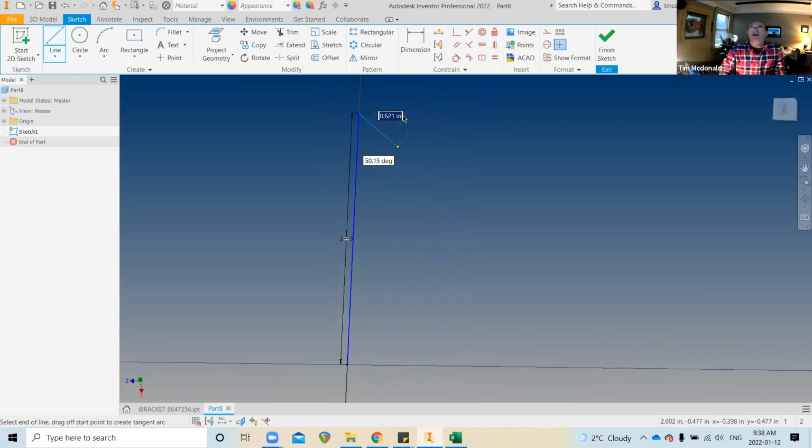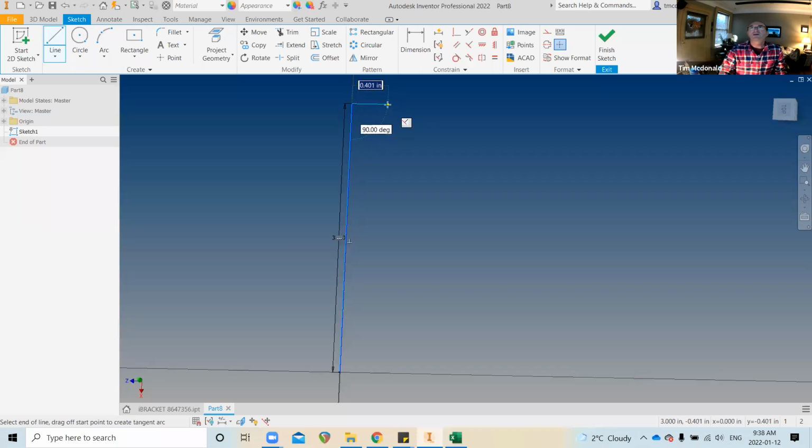And let's just go over perpendicular, and I'm going to make this one flat. I'm just going to call this flat and equals 0.5. I like to include flats on my gussets because it gives a welder something to weld around. It also eliminates that pointy edge, that pointy corner that could be used as a weapon if that was the case.